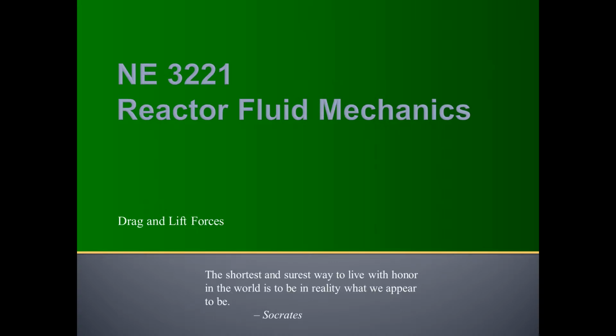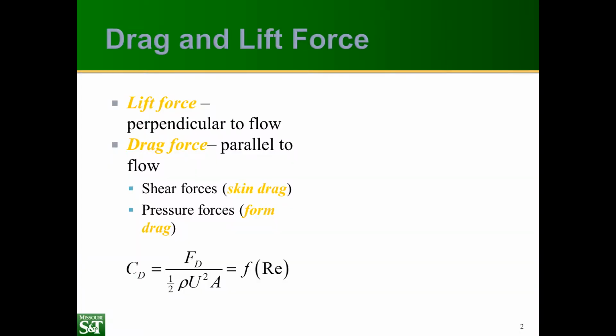We're going to very briefly talk about how we predict drag and lift forces on objects in engineering. Now we all know that a body that's moving through a fluid experiences some force. We divide that force into two components based on its direction. The lift force is perpendicular to the flow, and the drag force is parallel to the flow.